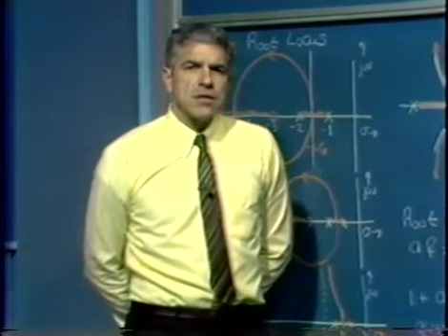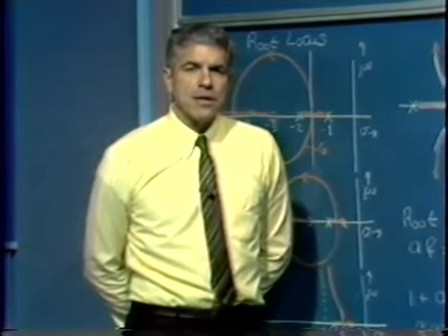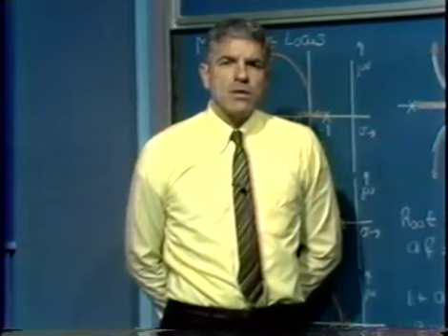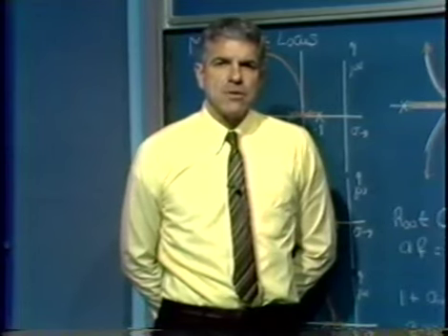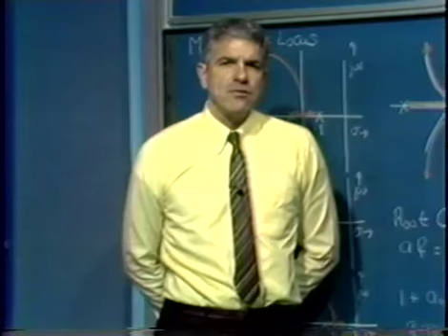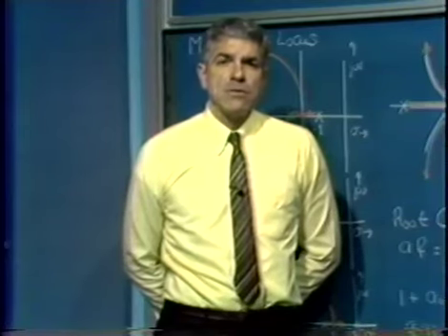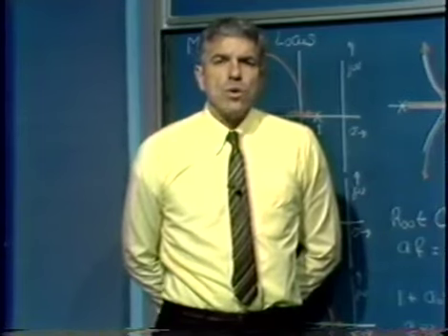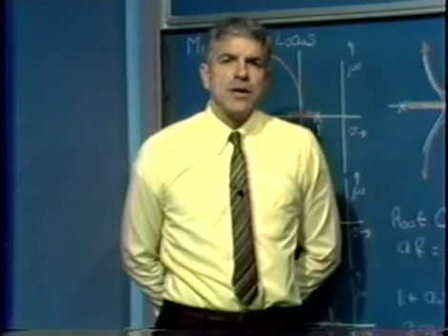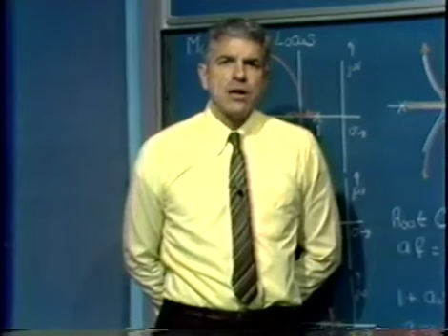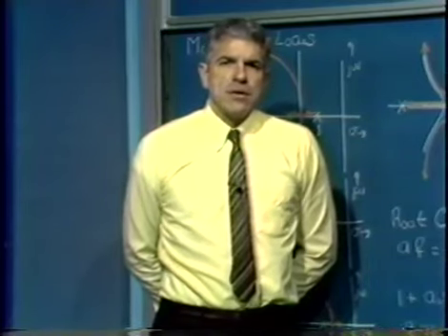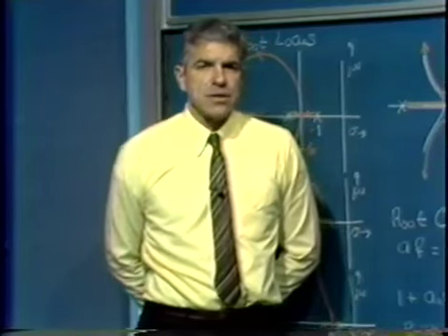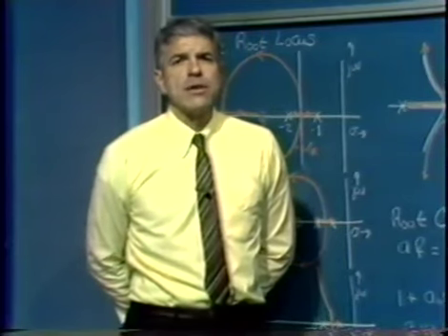There's a rather interesting extension of root locus techniques that's worth mentioning. Let's think back to what we're really doing in a root locus development. We start out with the poles and zeros of the loop transmission, and we have a single degree of freedom. We can change A0, F0, which is the magnitude of the low frequency loop transmission. And what we get is the way the closed loop poles of the system vary as we change the A0, F0 product. Well, one can extend this analysis, and the resultant extension is called root contour, or the resultant diagram is called a root contour diagram.